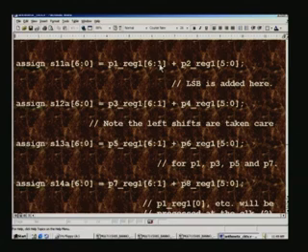So we start with P1 through 6, and P2 is shifted left by 1 bit and then added, and that is what we are doing here. We said that in Verilog it is very easy, you do not have to do any shifting operation. Within the addition we can do the shifting also, without any clock penalty. That is the beauty of Verilog.